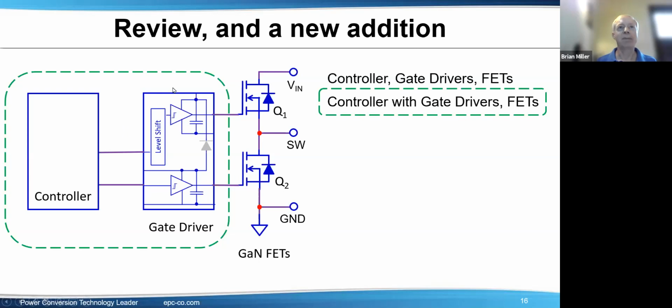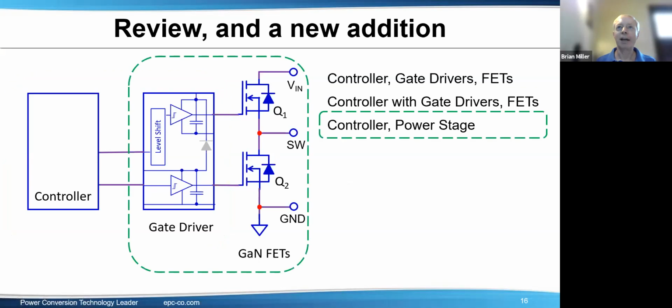And using some of the techniques in the previous slides, to make the built-in gate drivers work with external GaN FETs on those type of controllers seems to be growing in popularity. So this is one kind of division. A new kind of division is to instead take the gate driver and combine it with the GaN FETs, not just two die in one package, which is done and has been done, and there's examples on sale for that, but also a new one is to put all of this in GaN onto one chip. So let's go to the next slide.